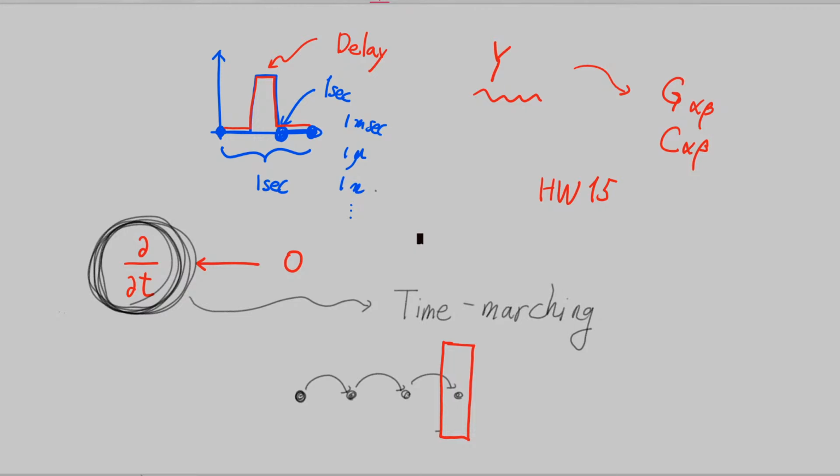Previously you just neglected any kind of transient effect, so just considering the present bias condition was enough for your application. But think about a fully functional transient simulation: then not only the present status but also your previous status will have an effect on your solution. So that is the point.